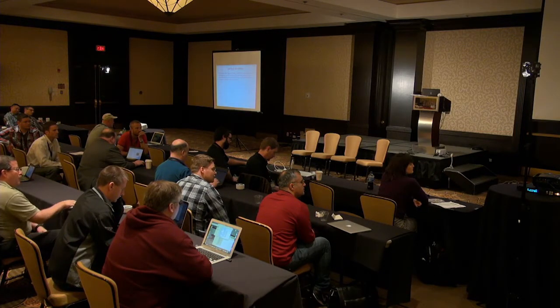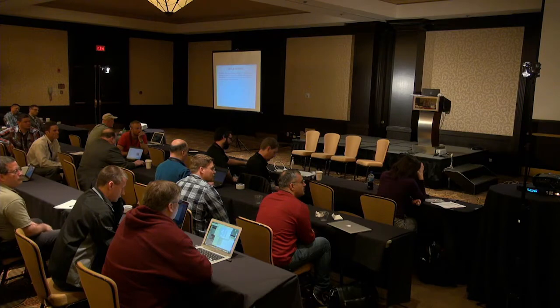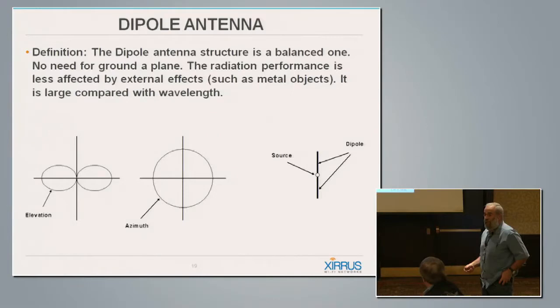In the case of the cellular band, the efficiency of the radio with the antenna is only 20-something%. So if you transmit 1 watt, you might be really transmitting only 200 milliwatts effectively. So very inefficient.